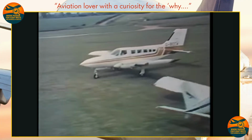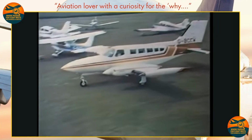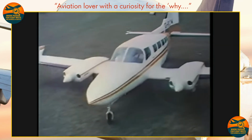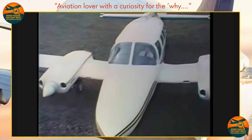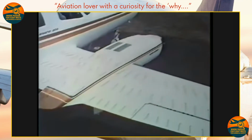The twin-engined aeroplane differs from the single-engined in several significant ways. The most important aerodynamically is the way in which thrust is usually divided by mounting the engines on the leading edges of the wings on either side of the fuselage. This has the effect of directing the slipstream of each propeller over the wing itself, thus augmenting lift over a considerable proportion of its span.